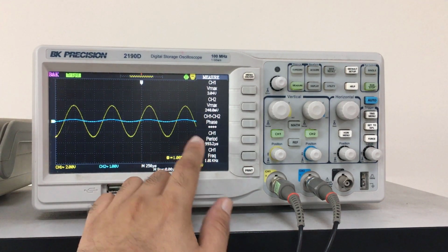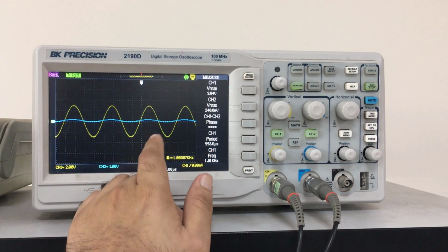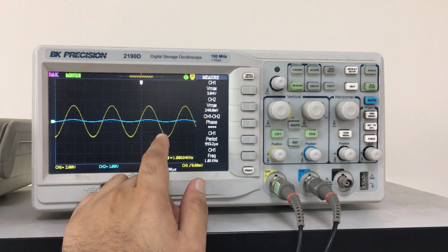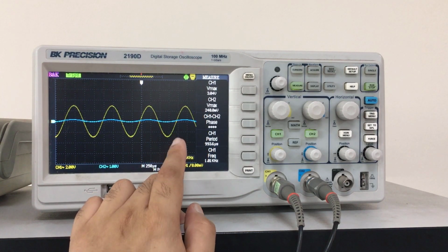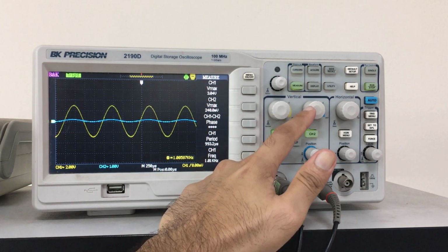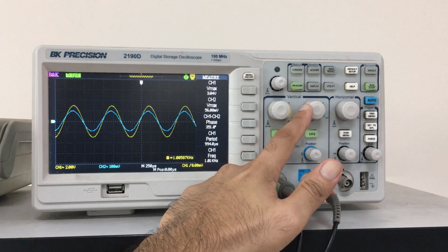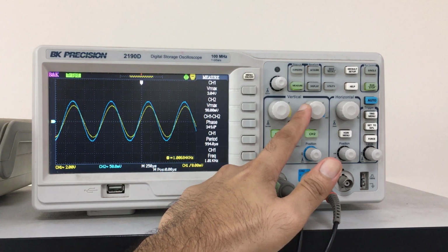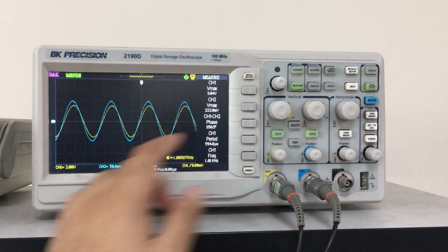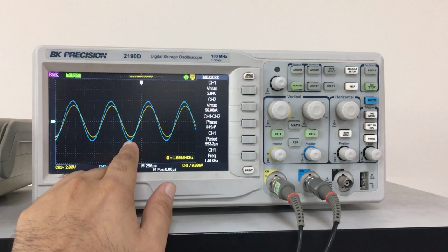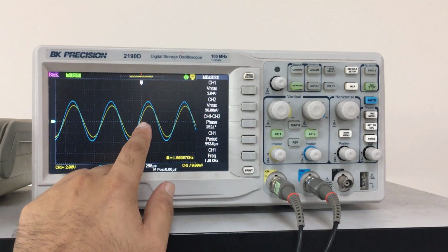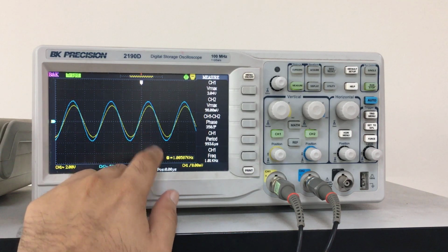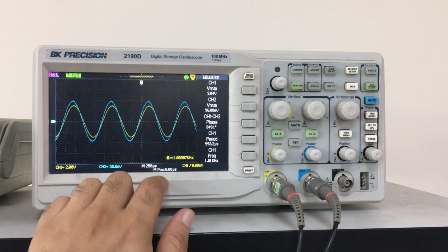So from channel 2, we'll measure the voltage drop across the sense resistor, and we'll also calculate the phase. As I mentioned earlier, if the voltage is low, we should increase the time division. This is the maximum utilization of the screen that we'll get for channel 2. So we'll record the values in this position and then continue with our calculation.